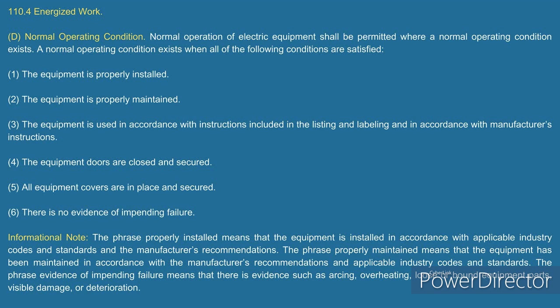It depends. With NFPA 72, almost always the manufacturer's instructions override NFPA 72. But just to throw a little disclaimer out there, in no way can manufacturer instructions create a direct code violation.